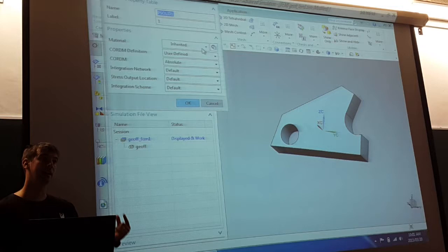Okay, so you can automatically see that that's how the region has geometrically been discretized, right? And the elements are tetrahedral, so on the faces you'll see triangular shapes. Right. So we've done our discretization, and we've also assigned our material properties. That completes the second stage of setting up the FEM model. We now need to set up the simulation model.